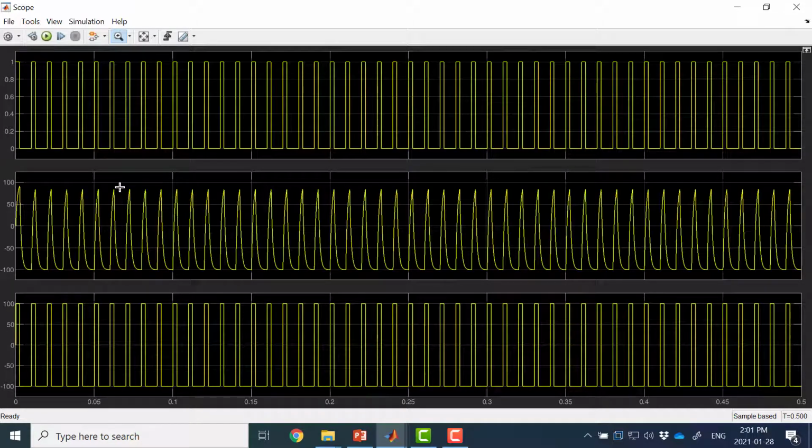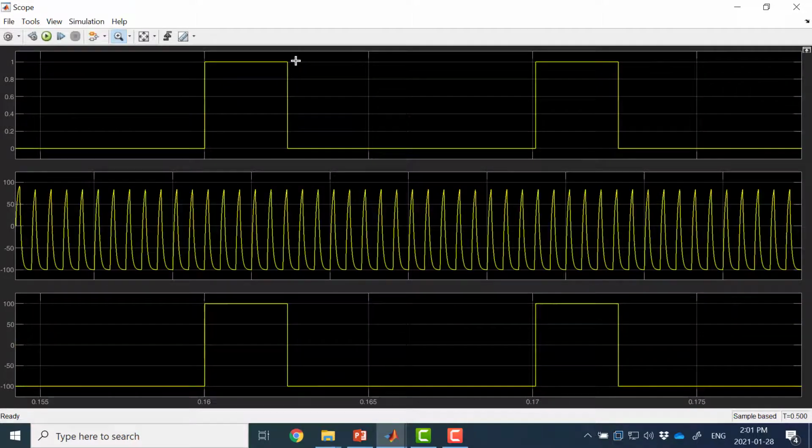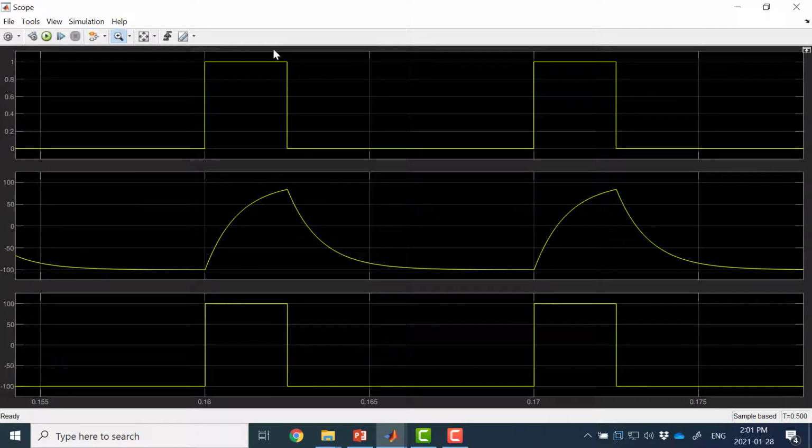Then I see that during one cycle from here to here, it's one cycle. During one switching period, I have 25% of the cycle my upper switch is on and I have positive VDC here, and for 75% of the cycle I have a negative VDC here. And if you average this one, it will be VDC over 2 times 2D minus 1.